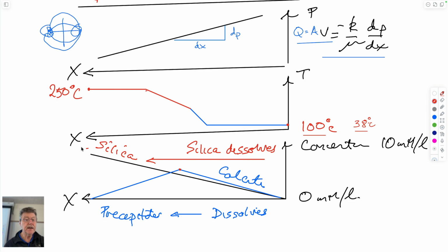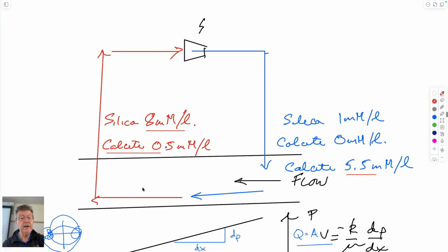So this potentially comes out at a high concentration. This potentially comes out at a low concentration, the water, because it's dropped it in the reservoir. And so when you bring it out of the reservoir, these might be the concentrations you have. You flash it to steam. If it goes from water to steam, it doesn't carry any of this, so it deposits it. It deposits it either in the piping, or it deposits it disastrously on the turbine blades and destroys it through that.